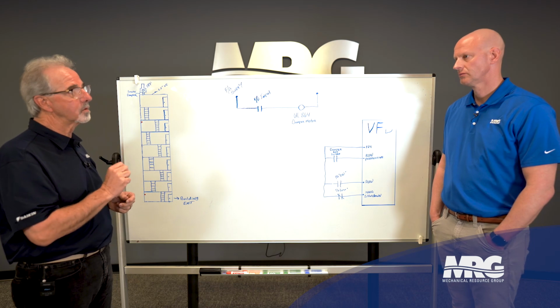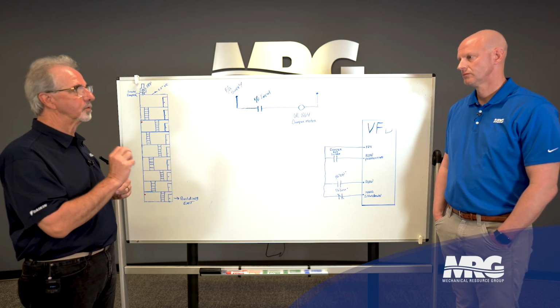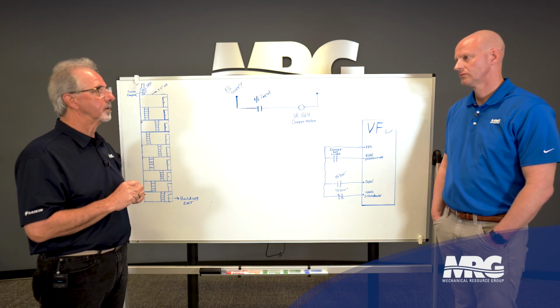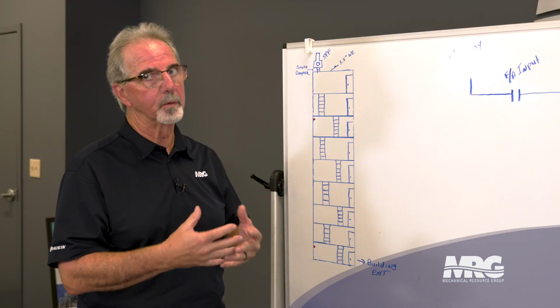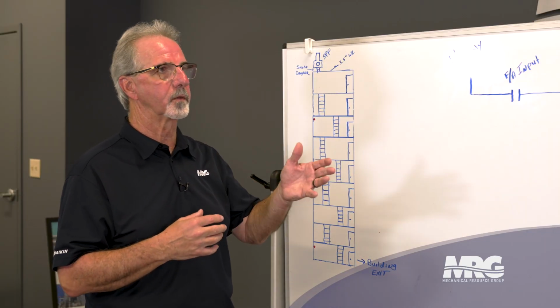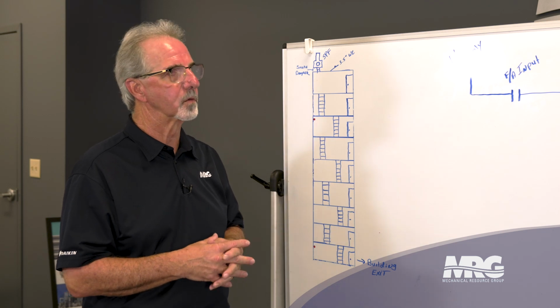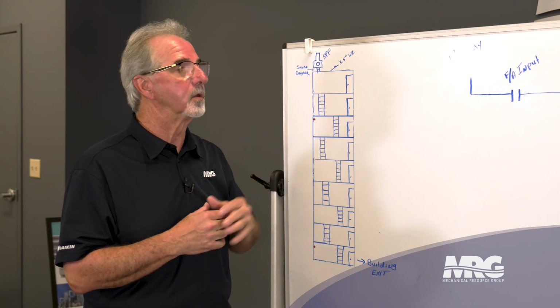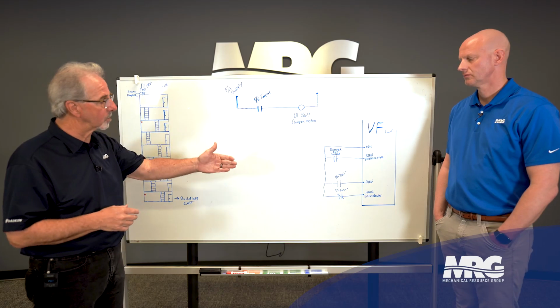There are situations where fire alarm wants to bring me the 24 volt. So again, get your scope to your mechanical contractor as soon as possible, because then what we do is we set the drive up for an external voltage coming to it, and we don't have to use the P24, we only use the 3 inputs.